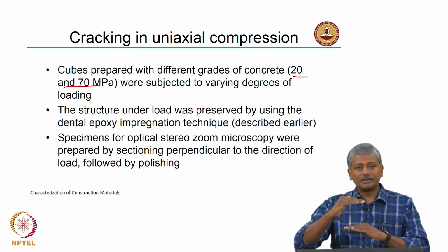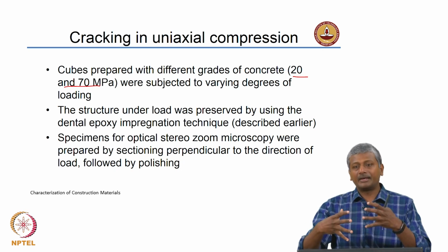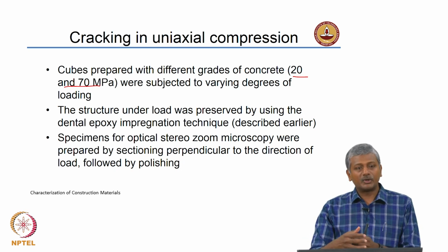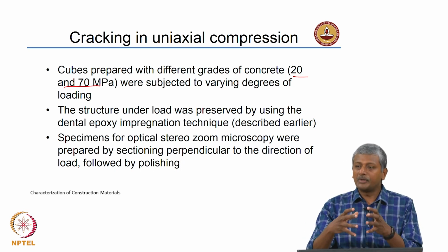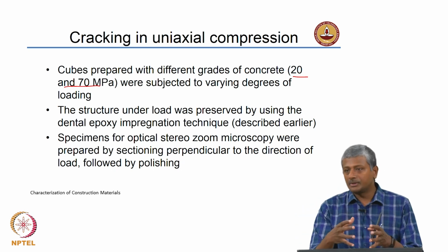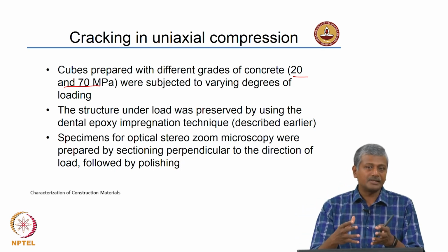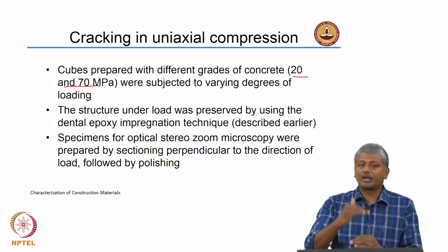So, at each stage, when the loading was on, encapsulation by epoxy was done to ensure that the cracks would be preserved when unloading happens. Of course, not all of the cracks will be preserved, but at least some part of the cracking should be preserved when unloading happens.